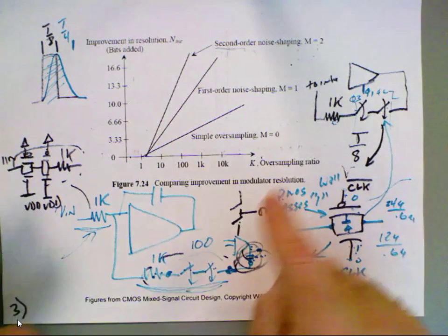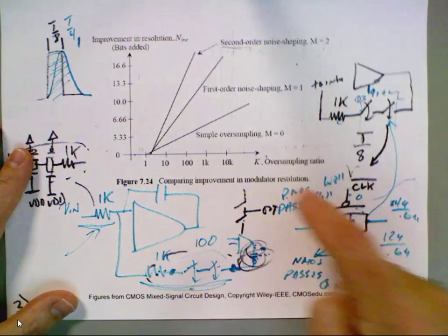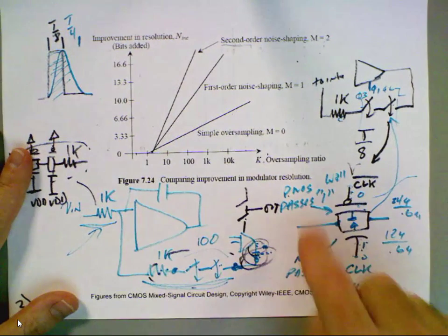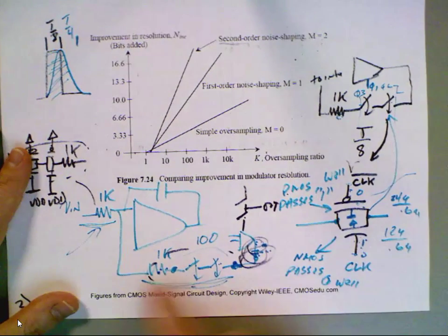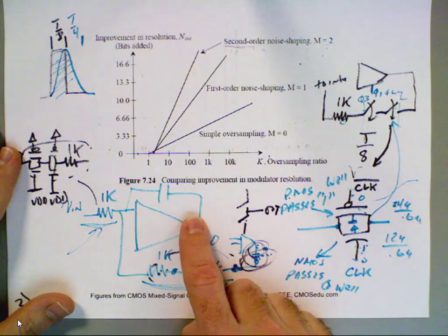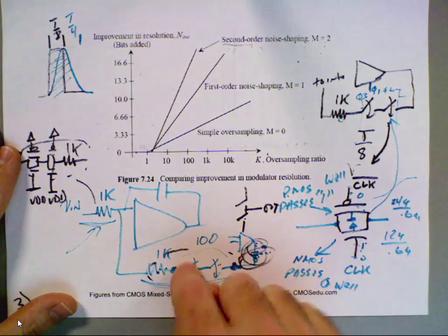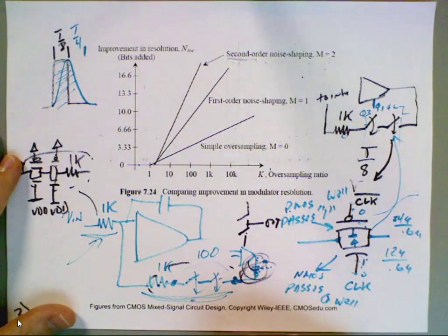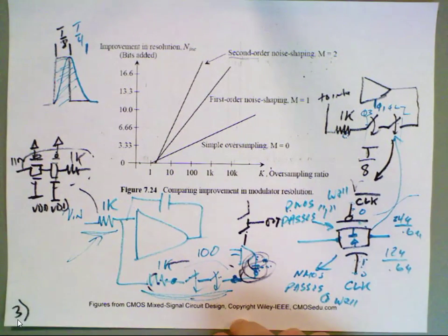Yeah, you can troubleshoot it, because if this goes up, it should slam those comparators to make the decision to feed back the signal. Now, if it's feeding back such a weak amount of signal, then that's likely causing it to be unstable. So you need to make sure you're getting enough signal fed back. All right, so hopefully the projects will go well.